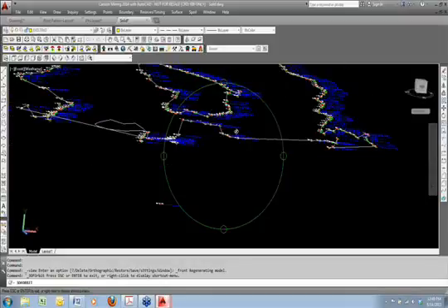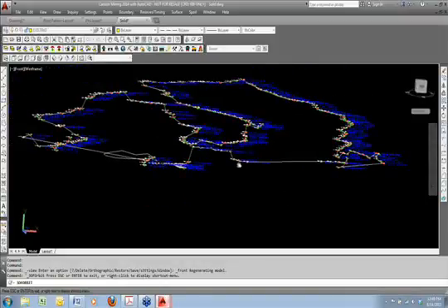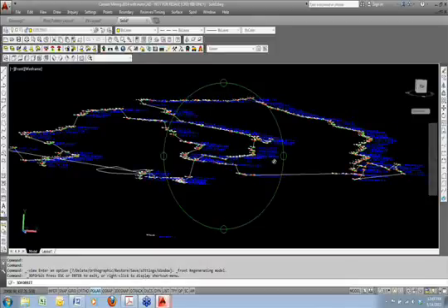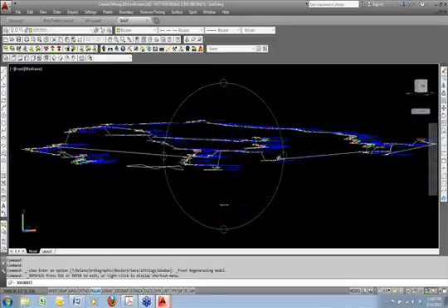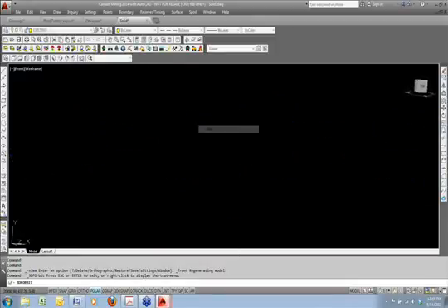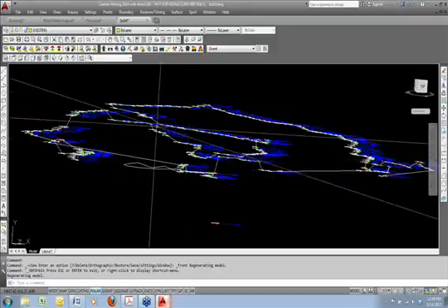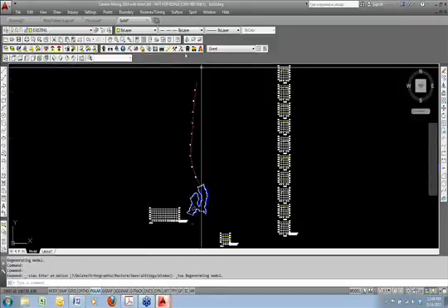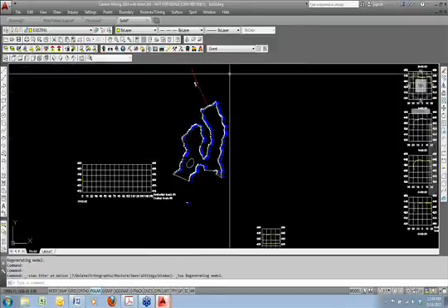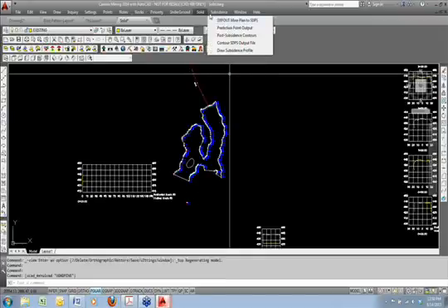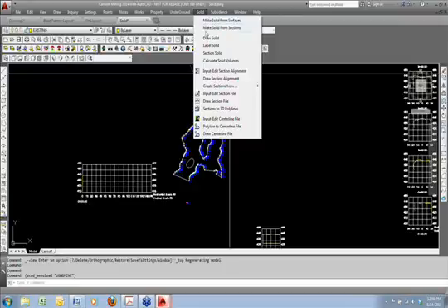And so this is the requirement on what it needs. It needs a 3D polyline around the rib, and also then points for the roof and floor to make the surfaces. So you make a surface of the roof, surface of the floor, and then this is your rib line. And in the underground module, we'll go ahead and run some of these steps. Switch over to underground, and here's the new menu called solid. Things for making solid from surfaces, from section, draw, label, cross-section it, and then ultimately get the volumes.